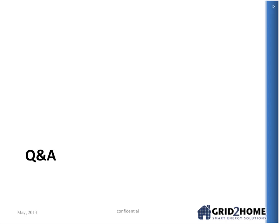But you also made the point that those meters that might be able to be migrated from 1.x to 2.0 may not be that full. Yes, so they have to pick. They have to pick and choose which function sets. So, for instance, depending on the memory available, you still may be able to implement flow reservation, but you may not be able to implement DER. Right. DER is distributed energy resources. It's a big function set. So it depends on your memory available what function sets you can deploy. So a utility will have to deploy one or the other, and if not, go to full 2.0. The nice thing is that the demographics that can afford electric vehicles can also afford an internet connection.